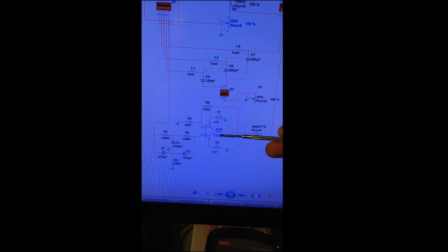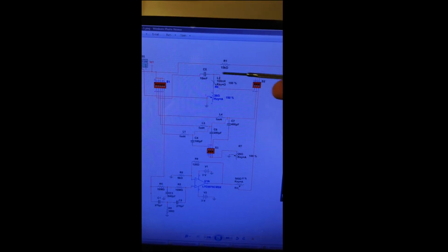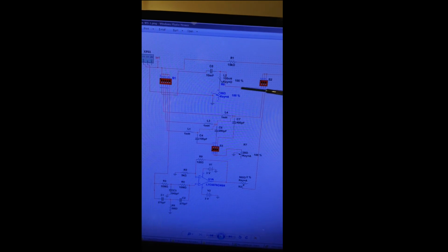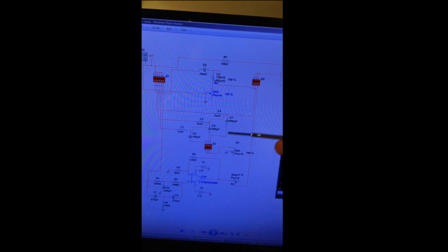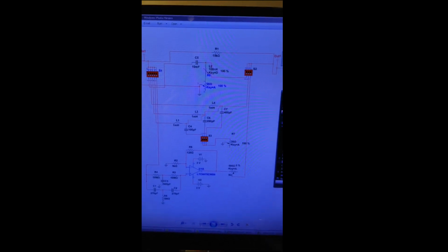One thing I should note that I've learned through the testing is that this op amp here, which is used to amplify the signal back to normal, there really needs to be an op amp here and here in the low pass and the high pass filter so that we can introduce a more dramatic effect of the roll-offs of the lows and the highs and amplify the signal to bring it back. But I just learned this last week in testing, so I definitely don't have enough time to reintroduce two more additional op amps into my design.